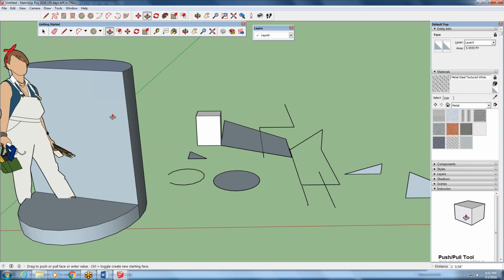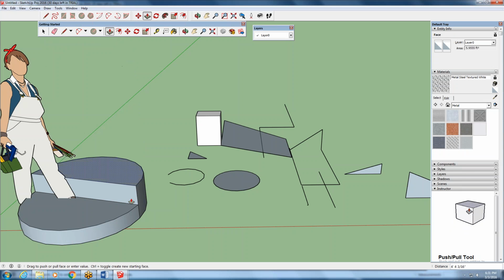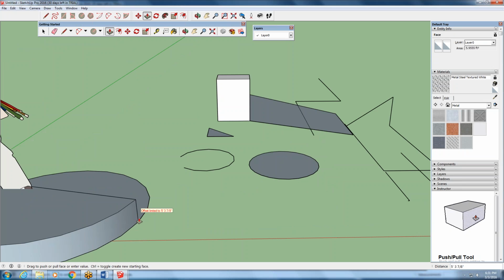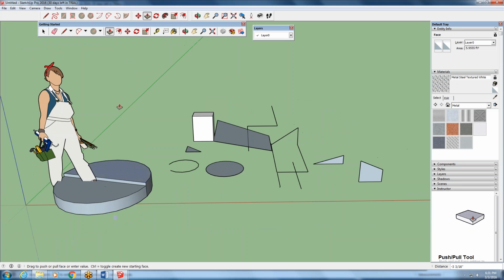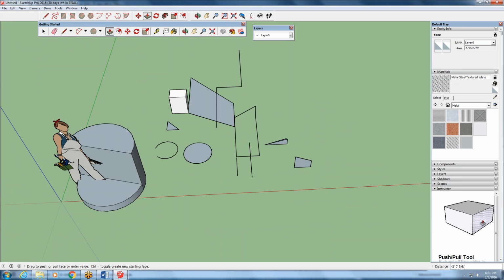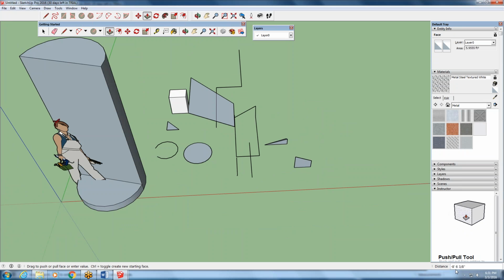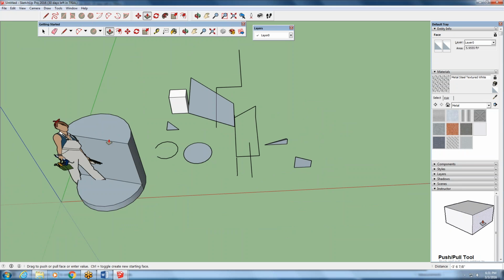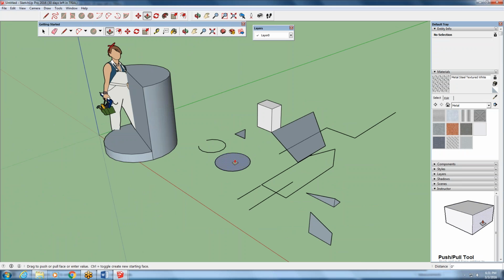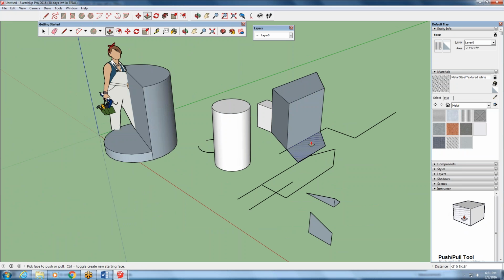You just click again to lower and raise. And then notice it says offset limited to this. Sometimes you'll get that. It's whatever the lowest height was. But you can snap it up and continue to go as high as you want. Come to the middle. Just pay attention to the distances. You know, if you were doing cabinetry, you want it at 36 inches or 42 for a different counter height. It's very slick. Easily allows us to break these shapes up and start drawing things.